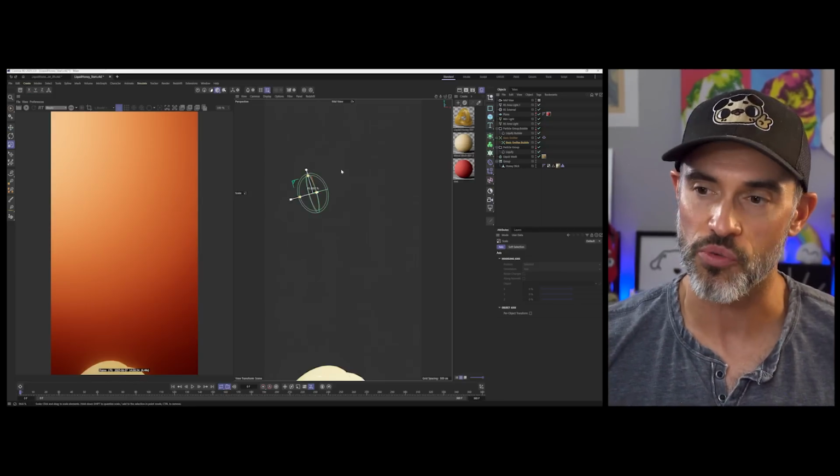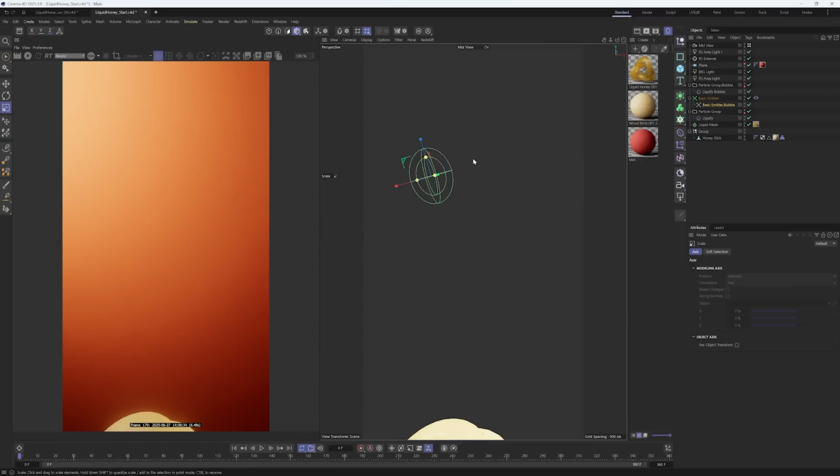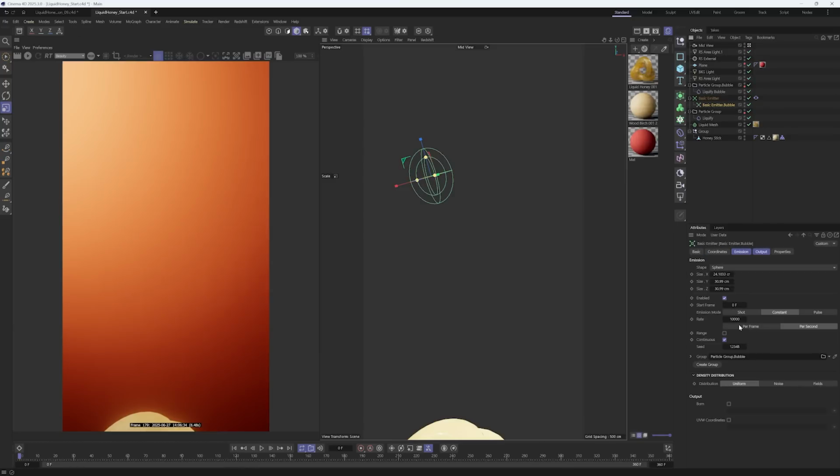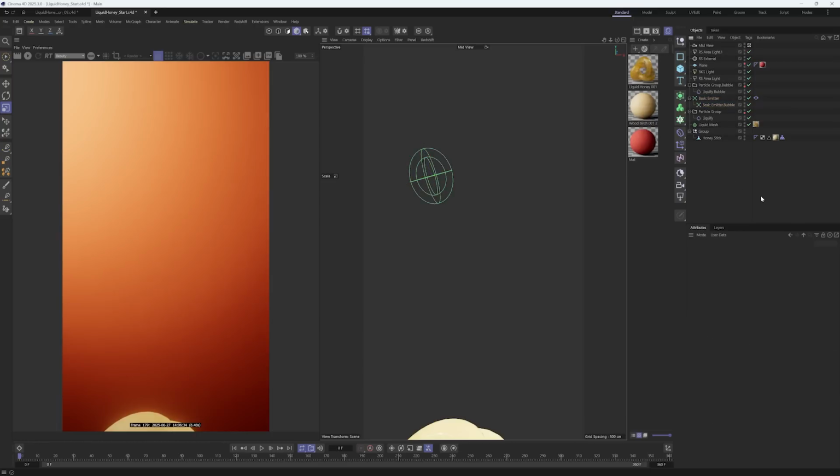So what we're going to do is just shrink down the bubble emitter just a little bit, so all the bubbles, all the particles will be emitted inside the particles that are being created by our main emitter here. We also don't need 10,000 bubbles, so we can bring this down to, say, like 30, something like that. And then we also need to clone geometry onto these bubbles.